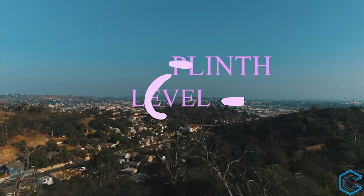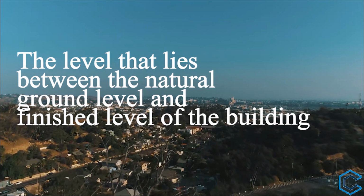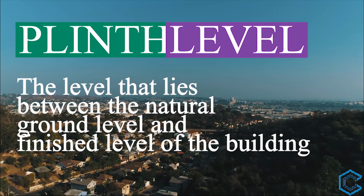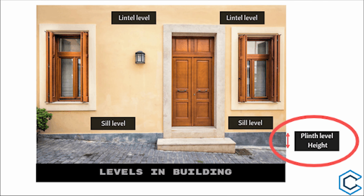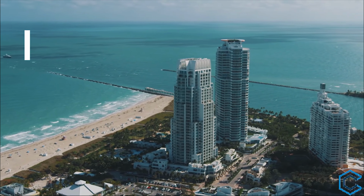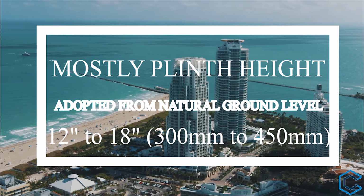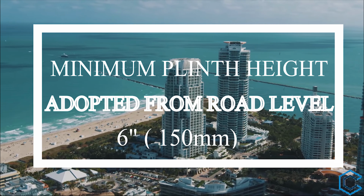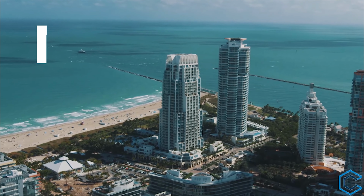Third, plinth level. It can be understood as the level that lies between the natural ground level and finished floor level of the building. Plinth height refers to the height of the plinth level from the natural ground level. Mostly the plinth height of 12 inches to 18 inches is adopted from the natural ground level. On the other hand, a minimum plinth height of 6 inches is adopted from the road level.